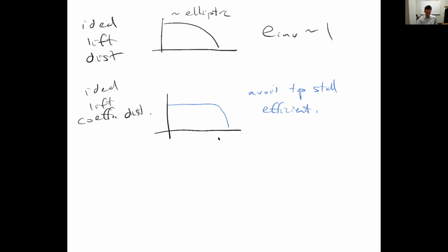It's also going to affect your lift coefficient distribution, right? Because CL is lift over qc. So chord is going to affect both of these. It's going to change the numerator, it's going to change the denominator. Twist is just going to change the lift distribution directly, but that's of course going to then indirectly affect the lift coefficient distribution. So these are going to be coupled. You're going to have to iterate and try these things a little bit.